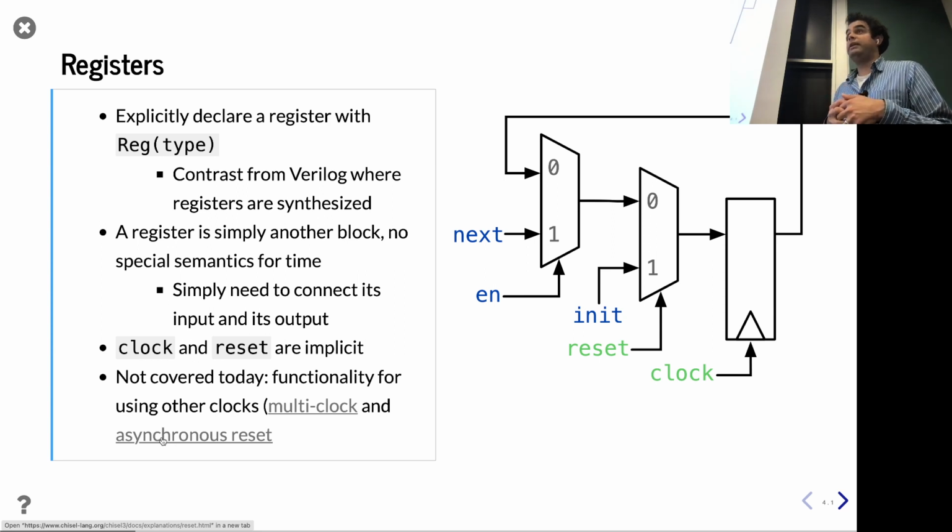Yeah, so the easiest way to do it would be to leave the register alone. It's still a positive edge triggered register, but then you just have an inverted clock. So what was a negative edge on the original clock is a positive edge on the inverted clock, and that's what you pass to the register. So it's still a positive edge triggered register, but it's being fed the inverted clock. So now you've made it effectively a negative edge triggered flip-flop.